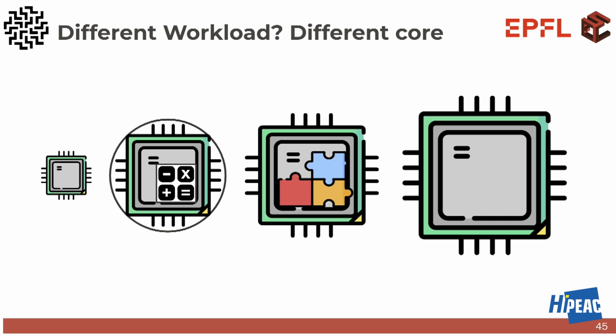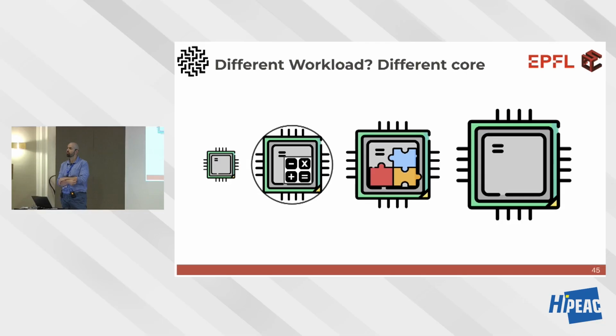I was wondering what was the trade-off to choose two pipeline stages? Empirically. You do experiments, and the goal was reducing the area, but still having a decent performance on the benchmark I had. So first you remove one pipeline stage, and you say, performance is still good. Let's go to 2. And performance is still good. Okay, let's keep 2. That's it. So it's experimenting. A bit of experience and rule of thumb magic, I would say.